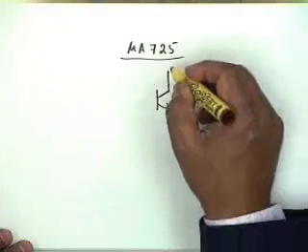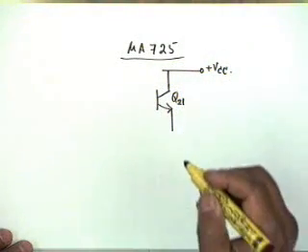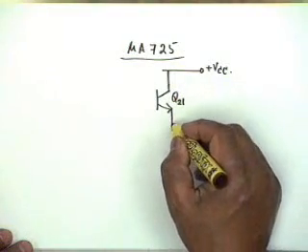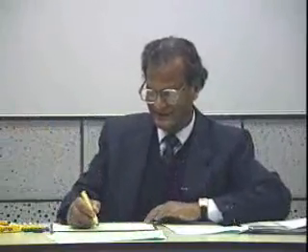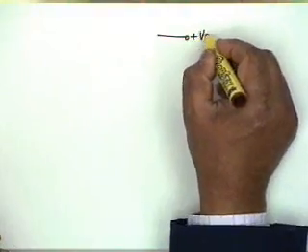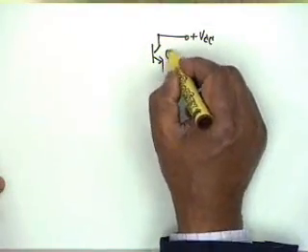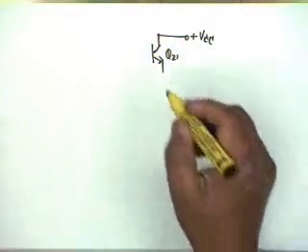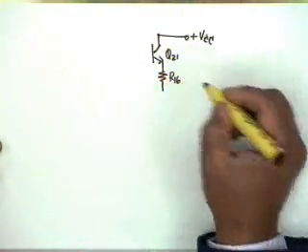Okay, the output stage Q21, and then this goes to plus VCC. I would like to start from another page, because it is a fairly large circuit and I cannot lose space. VCC goes to Q21, which is an NPN transistor. Then we have a resistance R16. This is a variation in the class B stage.